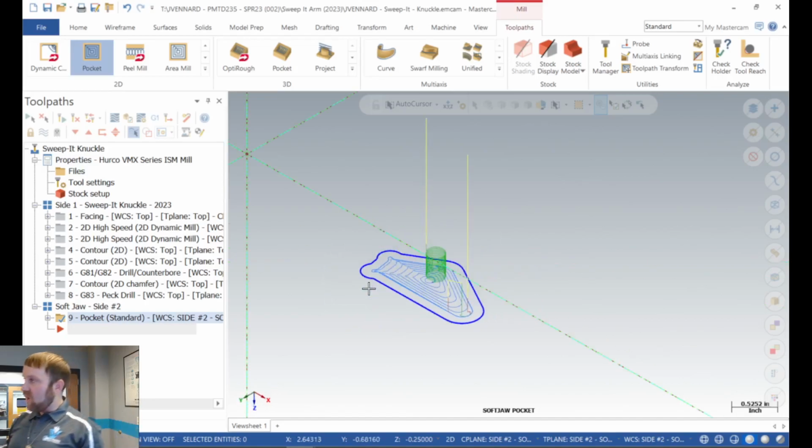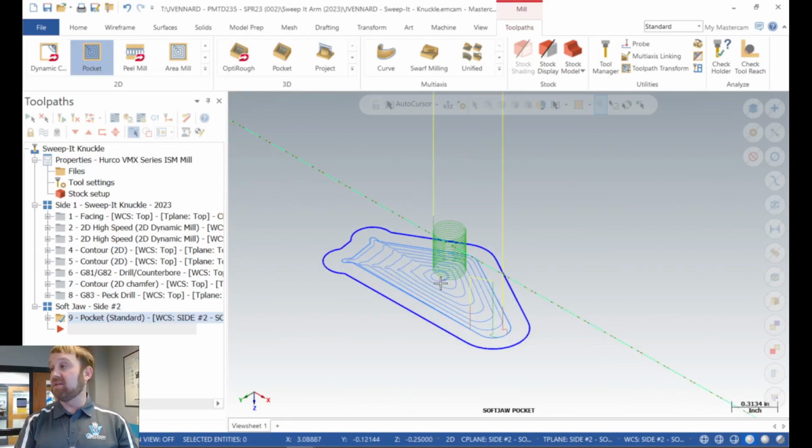We're not quite there yet. Who can tell me what they think we should fix on that toolpath? Pocket doesn't matter. A good practice would be to always do it counterclockwise. I clicked it the right way, but it's cutting on the right side though, and it's climb milling.